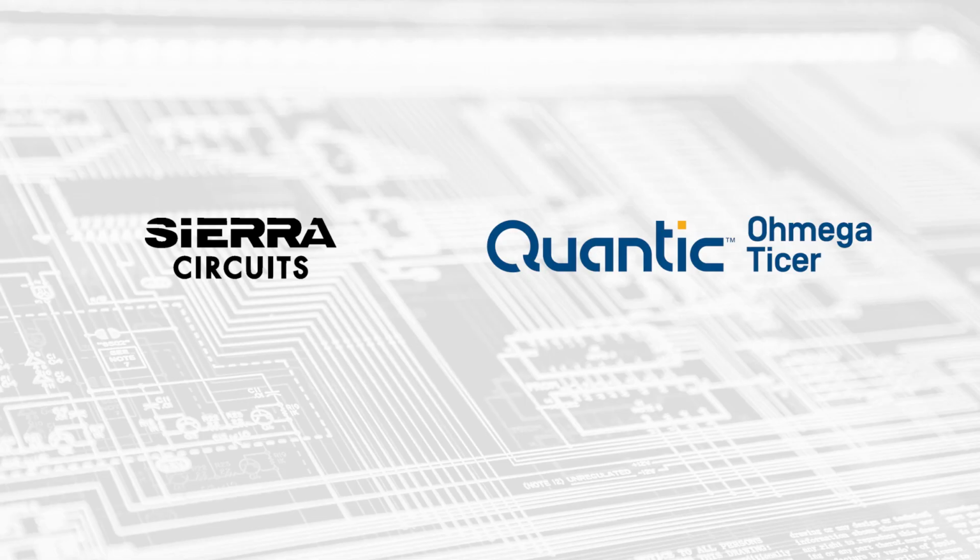Okay, I see the second question. And so the design rules for embedded resistors, towards power dissipation limits and tolerances. As I mentioned, we do have the calculator that can help, and it can tell you exactly how much power. And I have to just tell people, when we do our power rating, we take the resistor, put it on the laminate, and actually test it to failure in open air. So there's really no heat sinks anywhere. It's just on the laminate surface, and then we put power to it and see where it fails.